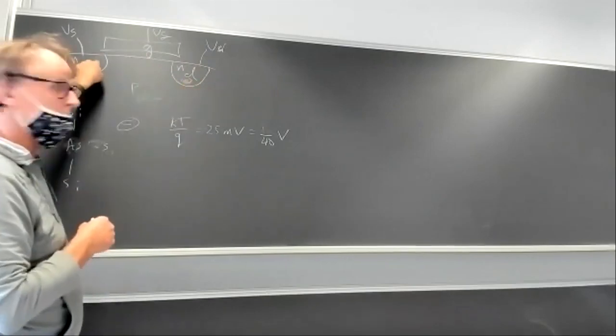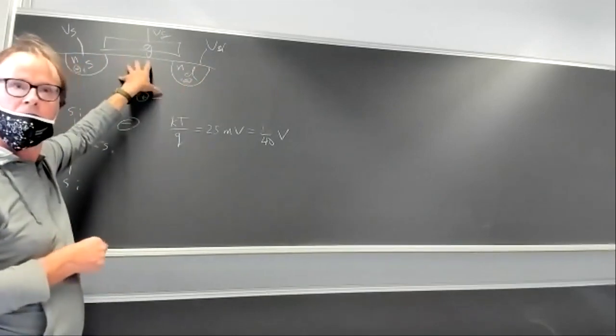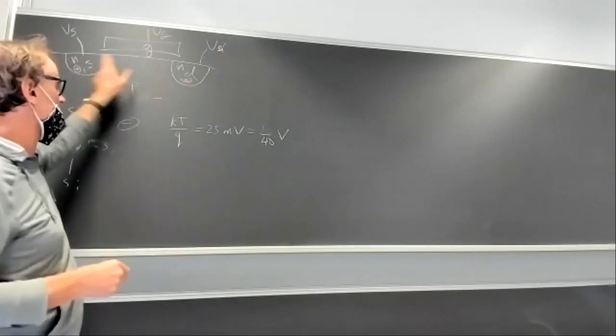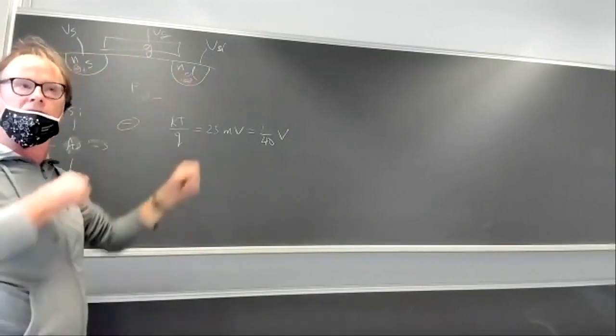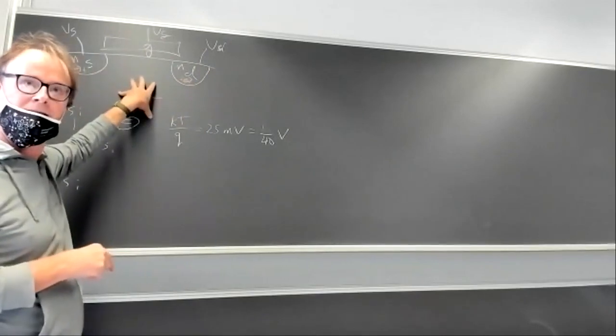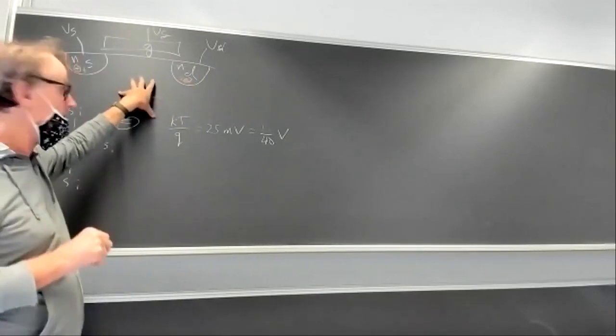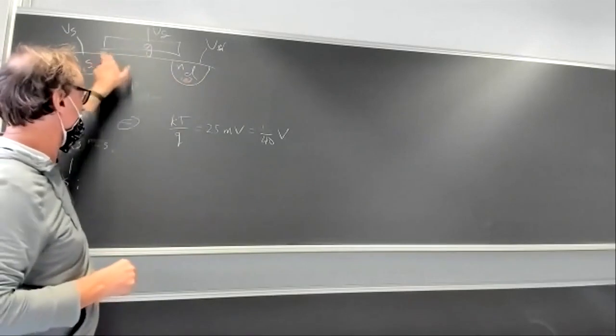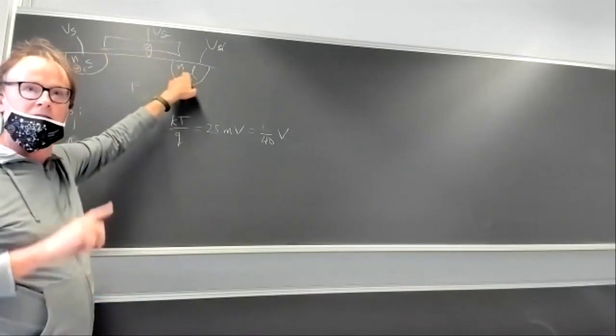They get pulled in from the source for this N FET. Why is it called an N FET? Because the source and drain are N type, and that's what flows through the transistor. The bulk is opposite, it's P. It has a lot of holes, but what flows through this N type transistor are electrons, not holes.